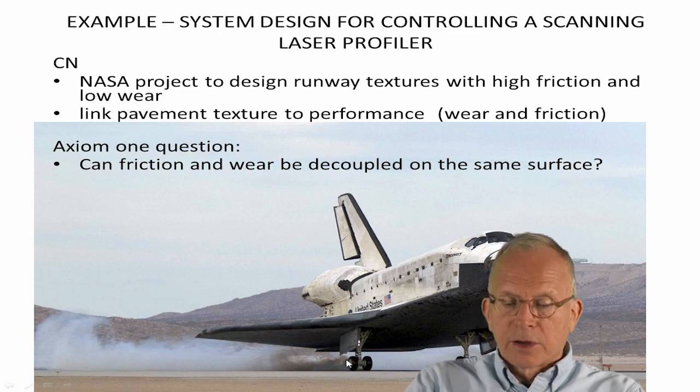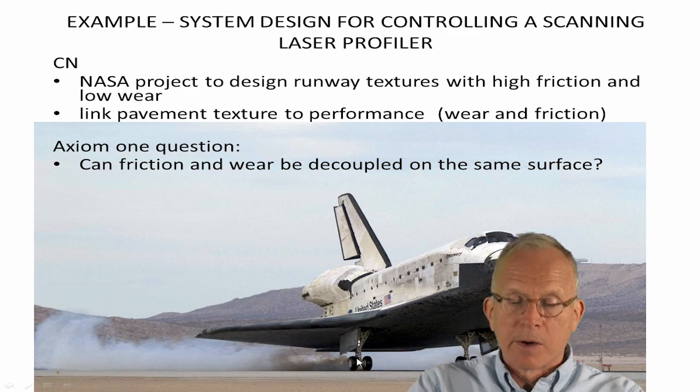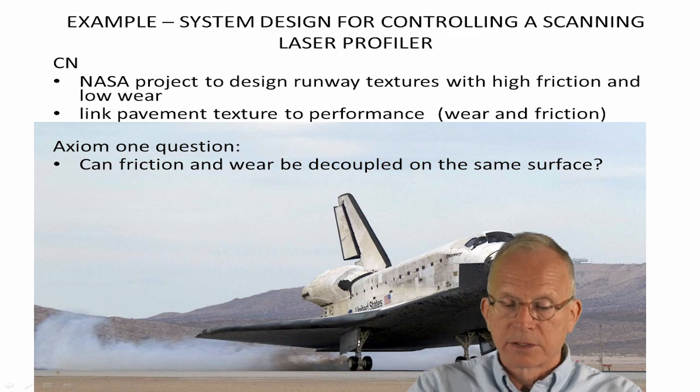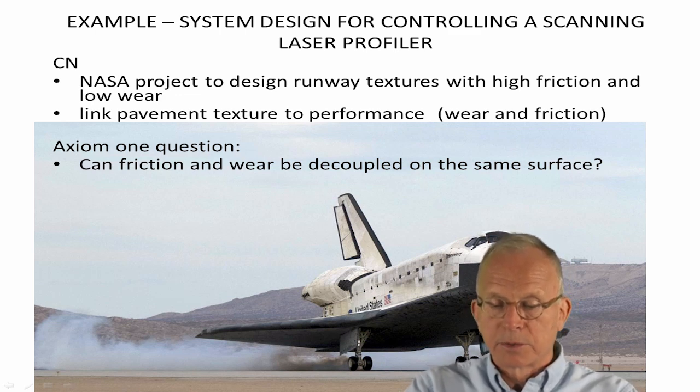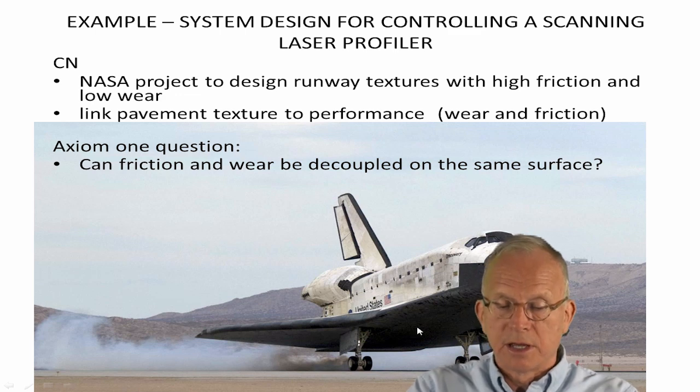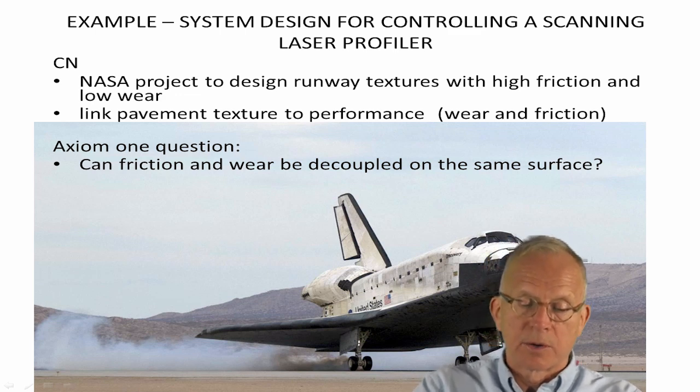So there was always a concern that they might have a blowout. And they did considerable testing on these, and they never had a blowout on this. Also, the nose gear is very light, and they would keep the nose up just as long as they could because the nose gear was even more undersized. And once this comes down, you can see you've got air pressure on the top of the wings, and the loads in the tires go up.